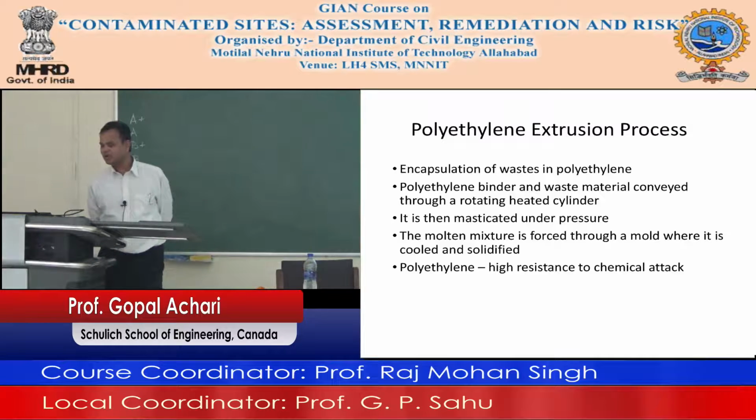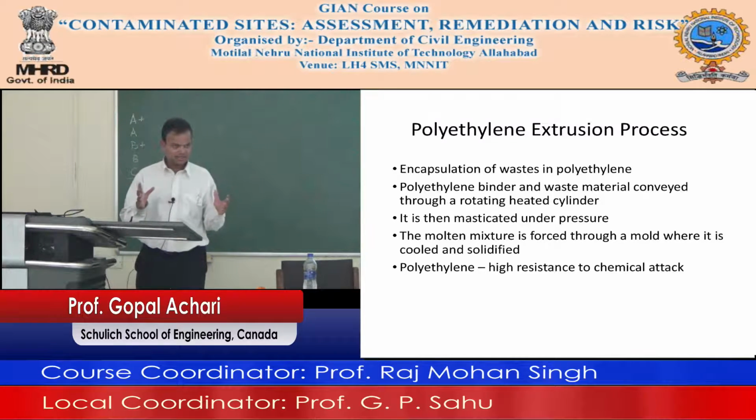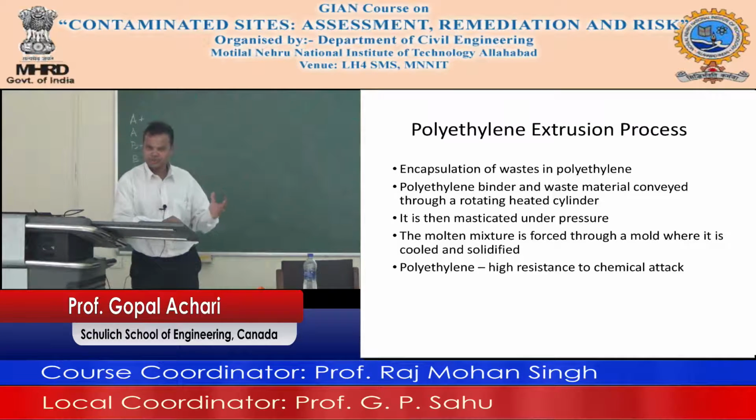So for example, if you use polyethylene, after you have done that, you have to chip out a little bit and do the TCLP test, and then show the regulators that under this aggressive condition of TCLP, it is not leaching. It is only under that condition that you can be confident that it is now fully encapsulated.